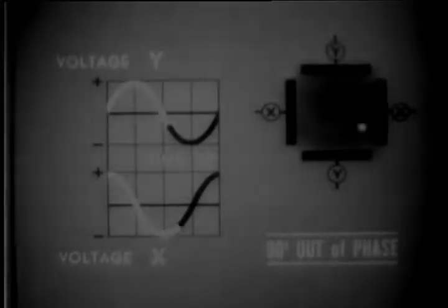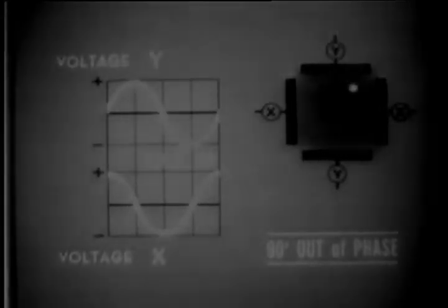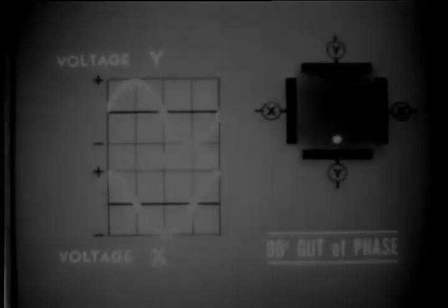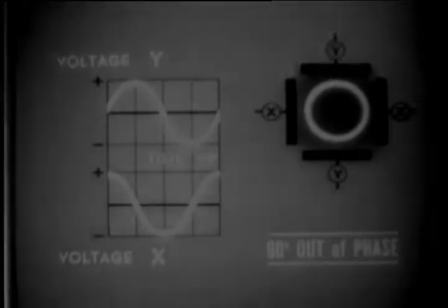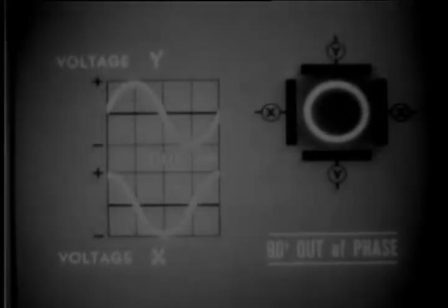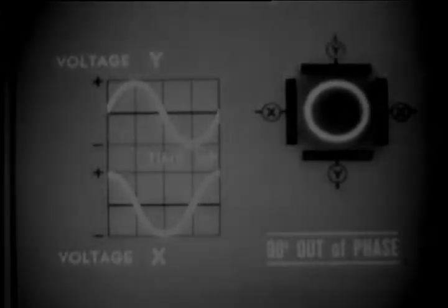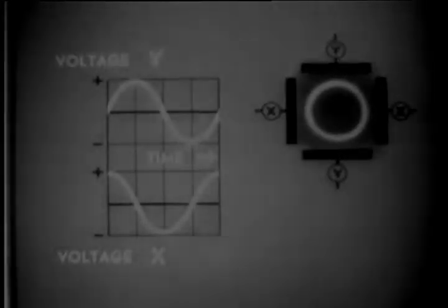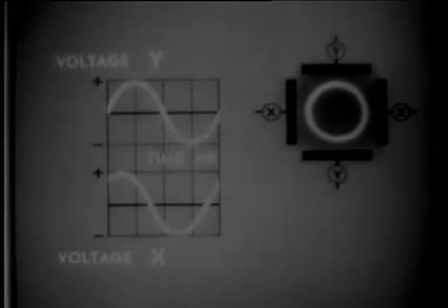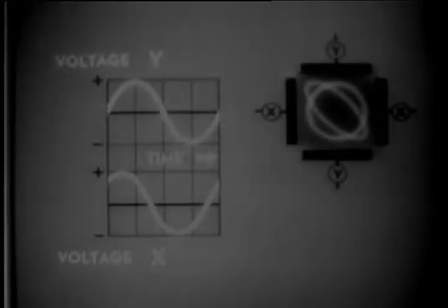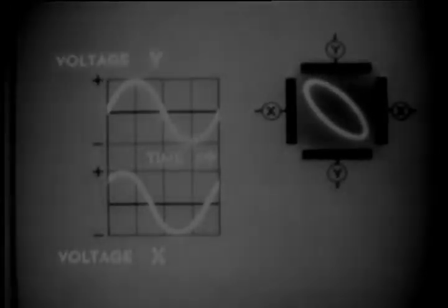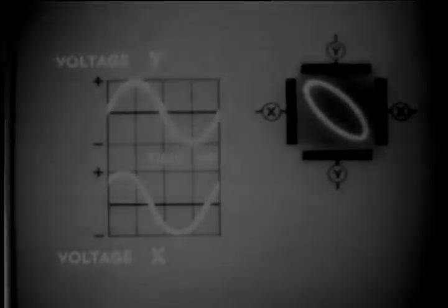As the cycle continues, the beam continues on its curved path, forming a circle. And of course, as the action picks up to its normal operating speed, you get the illusion of a circular baseline. Remember that this circle is the end view of a stream of electrons. If we vary the phase shift, the result will be some compromise between a circle and a diagonal line, an ellipse. But phasing isn't the only thing that will affect the shape of our circle.